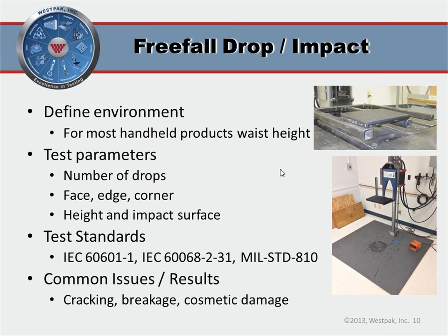Now we'll move on to some mechanical test inputs. The first one is free fall drop or impact. We have two different testers here on the right-hand side. The upper one goes into the floor, so it can do very low-level drops. Those kinds of laptops will drop down. The other drop tester below does higher-level drops above 18 inches all the way up to about 6 feet.